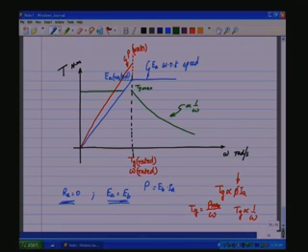So, there is possibility of obtaining a constant torque here, because the speed is less than the rated, and as the speed is less than the rated, IA can take a lesser value, and therefore, for any load one could achieve a constant operating point below the rated, but beyond the rated there is an upper limit for the torque, which will have a proportionality of 1 by omega. So, this would be the achievable maximum torque curve, the green line as I am showing here, with respect to omega.